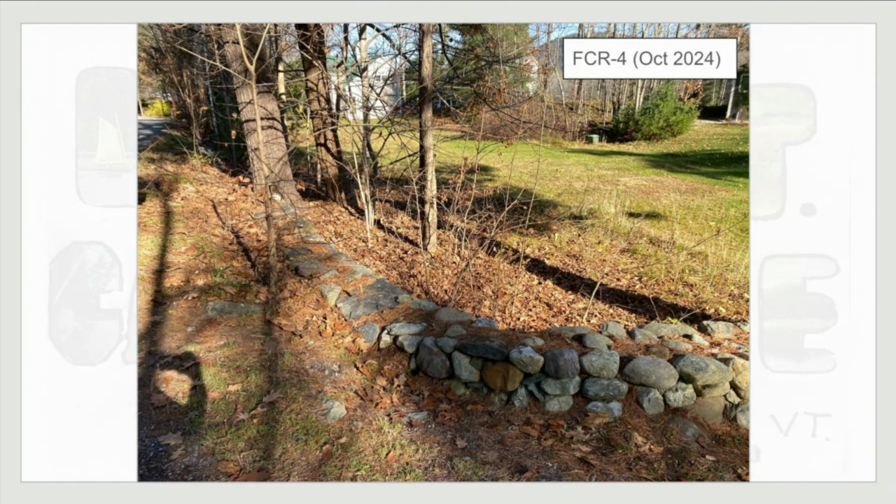so the idea with this practice is that we would divert a small portion of the stormwater into this space here. That would require a catch basin manhole that would take a certain percentage of this flow, because this space could not handle all the flow that's coming down that ditch. And it would divert it through a smaller pipe into this area, which is just off the right of way.